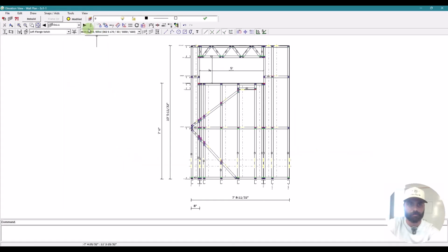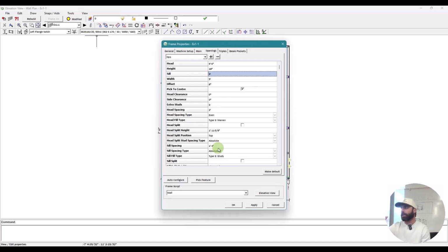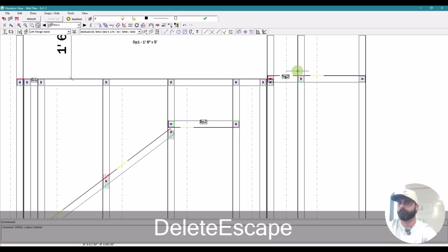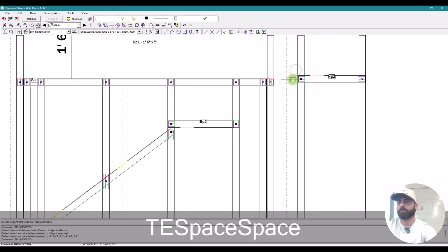It'll be for the machine profile, and if we know that we're doing a 5,000 square foot house that requires 1,000 square feet of a 4-inch strap, we can have the slitter cut us 4-inch strapping using our 20 gauge material. But that way, if we have these master coils of 18 gauge or 20 gauge, and we don't know whether the next projects that we're going to be producing are on a 3 5/8 or a 6, the coil is the same. So if we are doing a 30 or 50,000 pound multifamily project, and that's going to be 18 gauge, then we're going to get ready to have that slit.